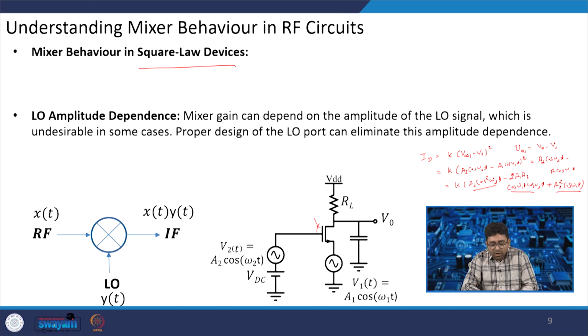Now, LO amplitude dependence. Here, your mixer gain can depend on the amplitude of the LO signal, which is undesirable in some cases. So, we need to do a proper design of the LO port, which can eliminate this amplitude dependence.